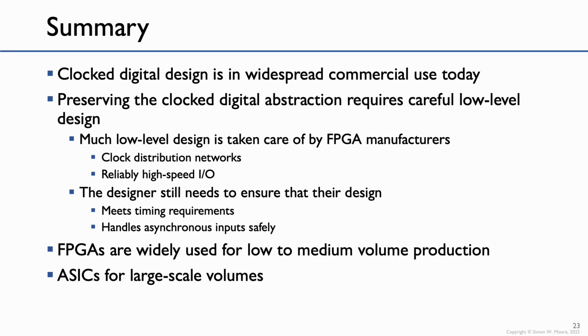Nonetheless, the designer still needs to ensure that their design meets timing requirements and handles asynchronous input safely to avoid metastability. FPGAs are widely used for low to medium volume product, and you're actually going to be using commercial tools. We're going to give you a route through the tools so that you get an idea what it's like to do this stuff for real.